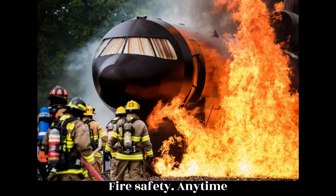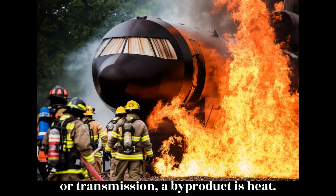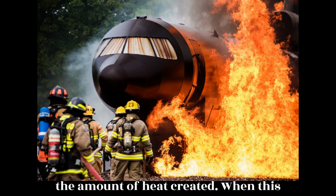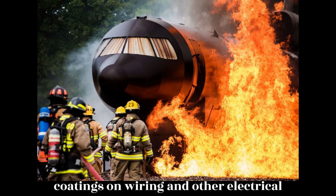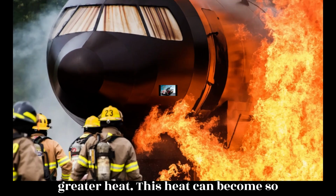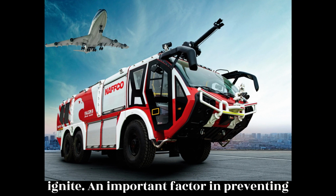Fire safety. Anytime current flows, whether during generation or transmission, a byproduct is heat. The greater the current flow, the greater the amount of heat created. When this heat becomes too great, protective coatings on wiring and other electrical devices can melt, causing shorting. That in turn leads to more current flow and greater heat. This heat can become so great that metals can melt, liquids vaporize, and flammable substances ignite.